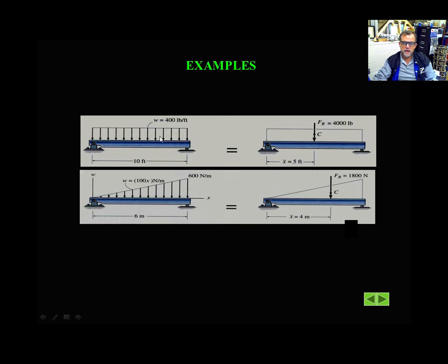Examples of rectangular loads are basically the self-weight of the elements, if the elements are constant in area and constant in density, like the roof, for example, which is usually rectangular. A typical example of a triangular load is the pressure of the water or the pressure of the earth, because every time that you go under the water, remember that triangular, let me go back here again.